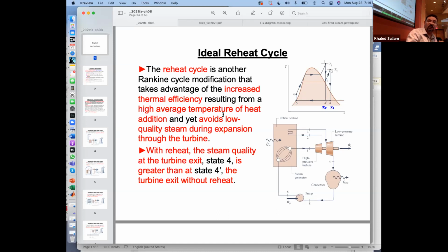So yes, you can see in the sketch, right? See how in B1 and B4, they are the same? But again, that's a really good point that in real life, it cannot be. All that pressure drop in multi-phase flow, we will calculate the pressure drop in the line when you are bubbling, and there is a pressure drop, but it's small compared to the pressure in that boiler.